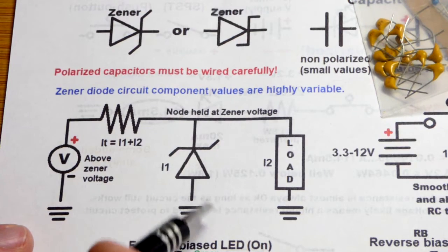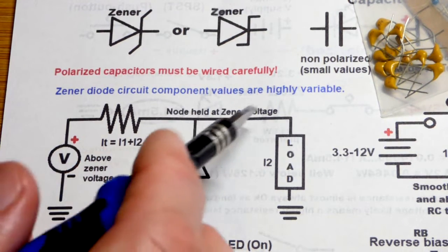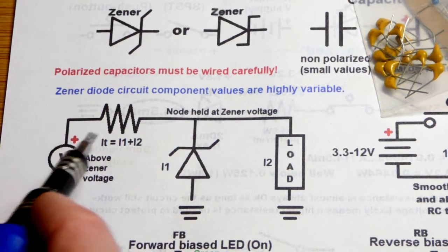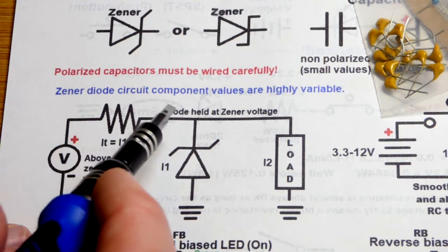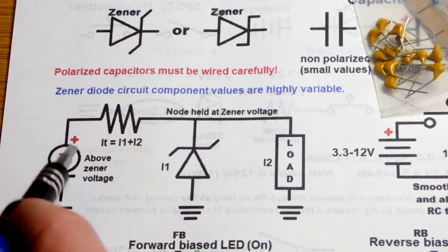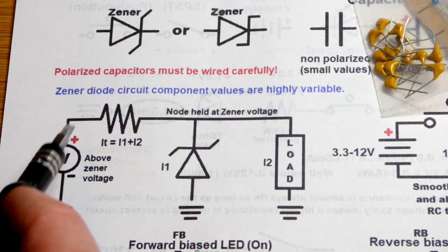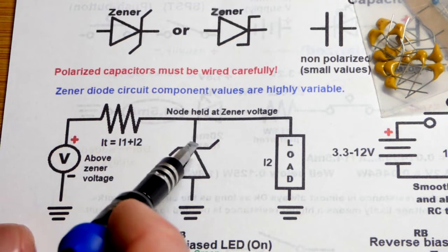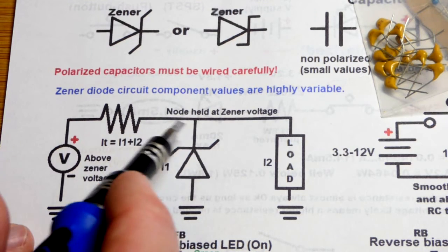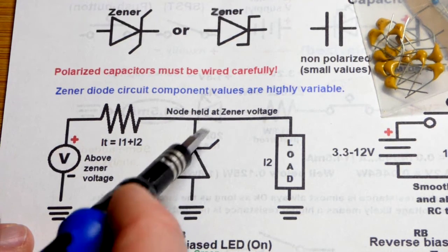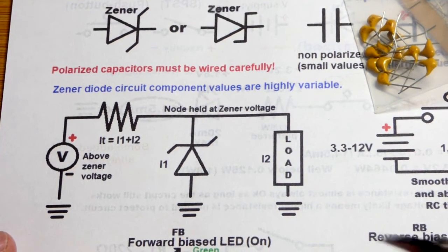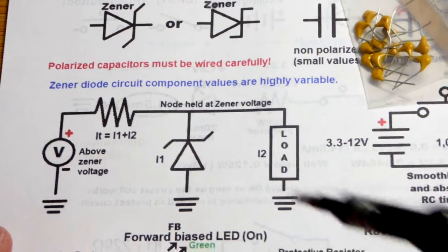At a certain voltage, it's going to block current. So it passes along that current, as the voltage over here is higher than it, because it loses a little power through the resistor, so it has to have a higher voltage. But even if the voltage wavers, moves around on this side, the Zener diode, as long as it's still higher, will pass current needed to hold a voltage at its Zener voltage. And so again, the load will vary and it will pass through there.